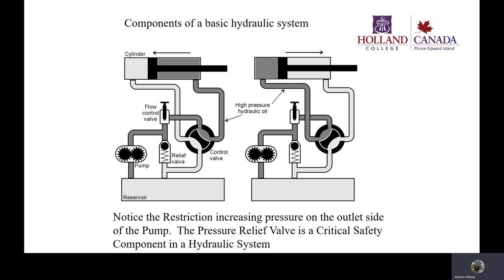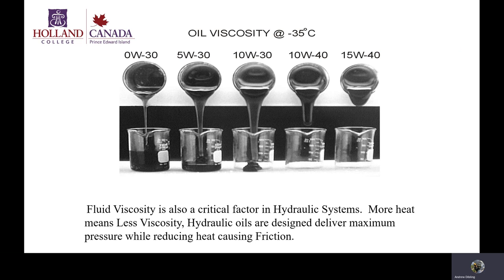And that's basically the long and the short of it on how hydraulic systems work. Speed for force, and pumps make flow, restrictions make pressure. Those are your big takeaways from this one.